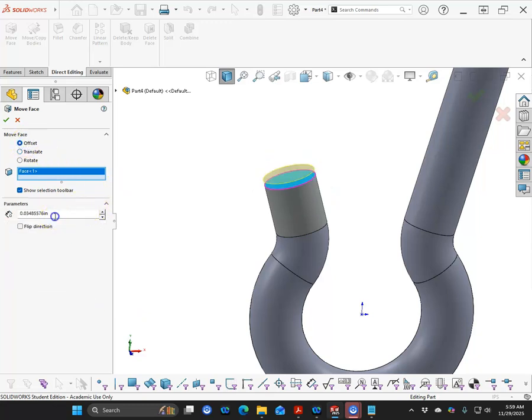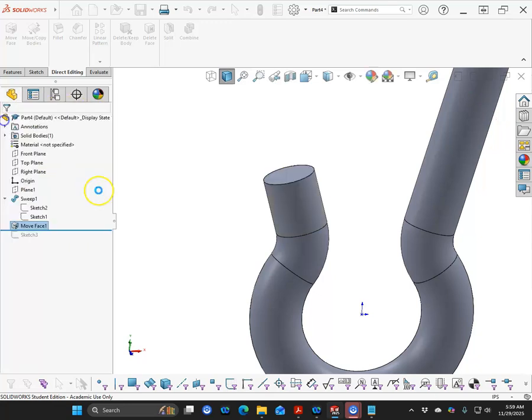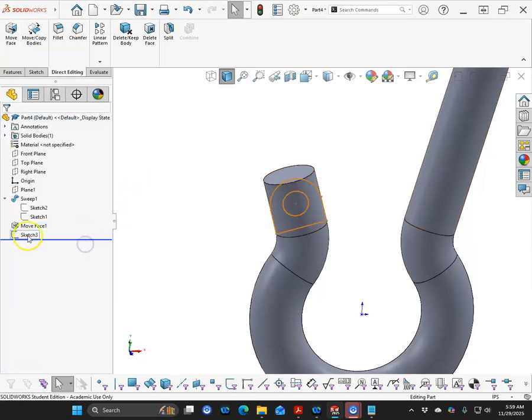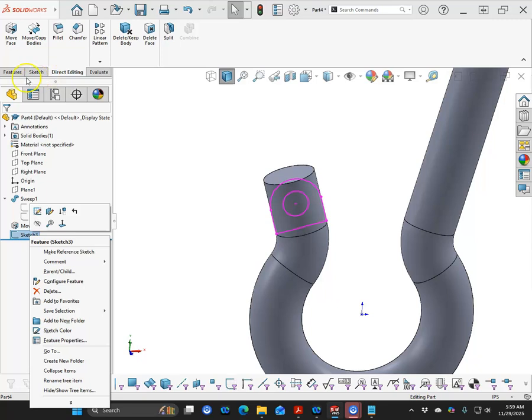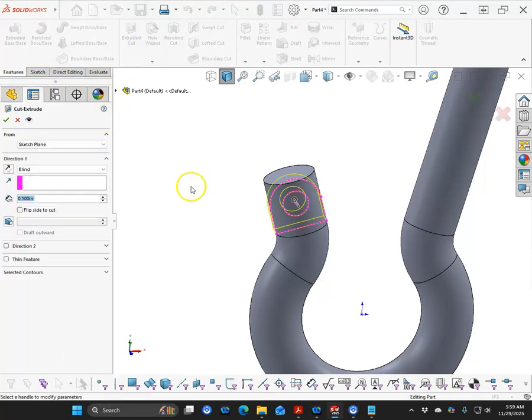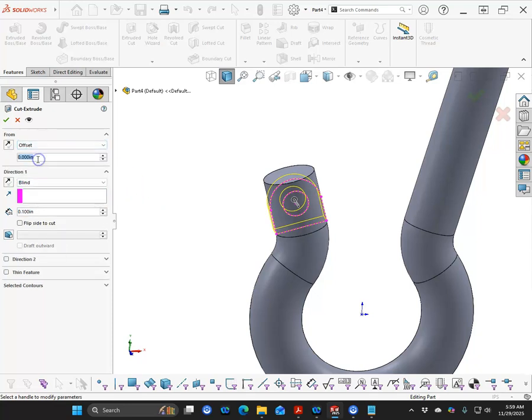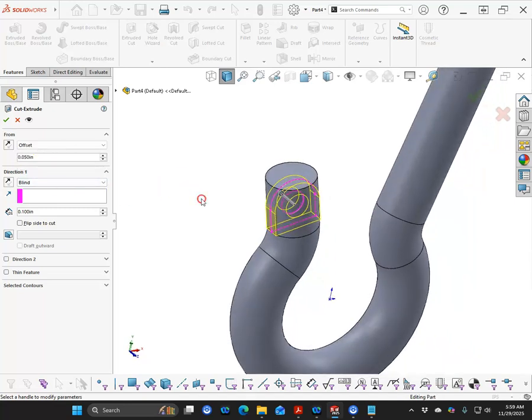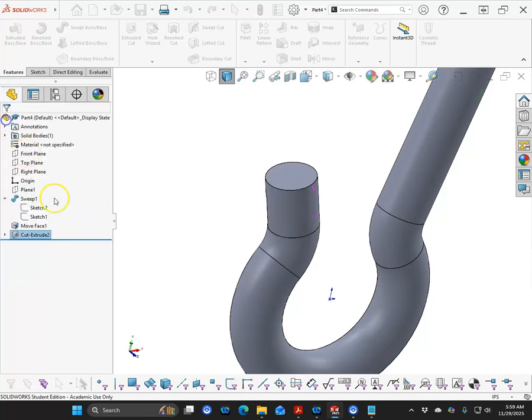We just want to do offset anyway. So yeah, 30 thousandths is plenty. We're going to leave a solid body when we make that cut. So I just need something to either make it a little bit bigger or a little bit smaller so that it has that offset. All right, 0.05. Let's reverse it, go up to next, and then hit OK.